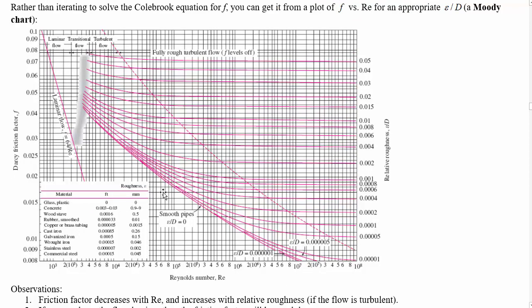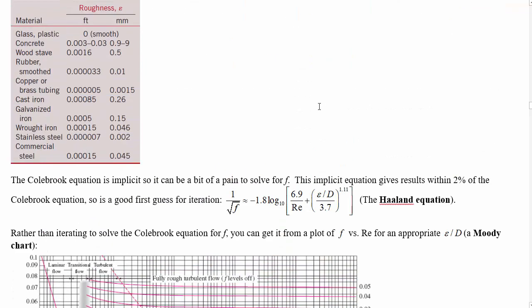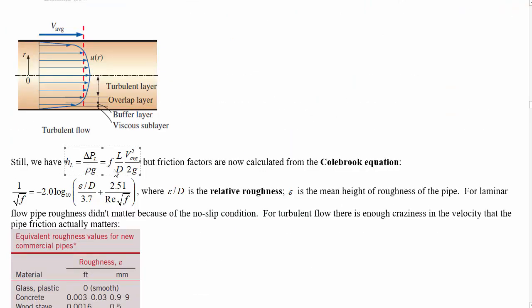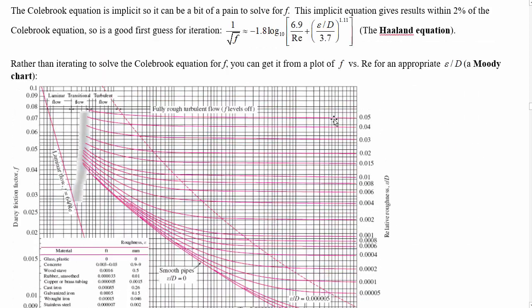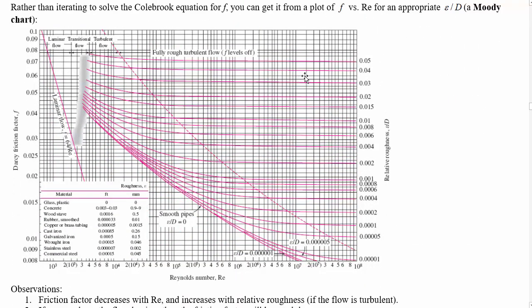friction factors, but the intuition it gives you about how friction factors work. So you can see that over here in this range, the friction factors are constant with Reynolds number. And in this situation, the head loss depends, with constant friction factor, on the velocity squared divided by the pipe diameter. Okay, that's fairly simple. It increases linearly with length of the pipe, decreases linearly with diameter of the pipe, and increases with velocity squared. That's only in the situation of extremely rough, turbulent flow.